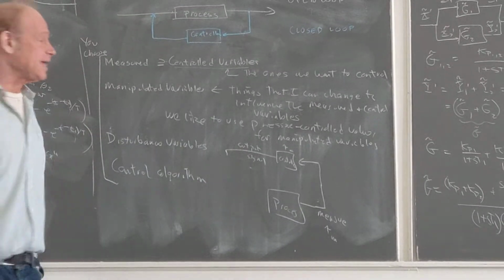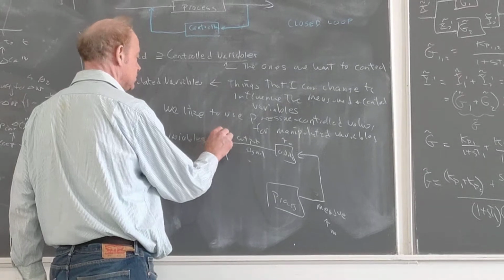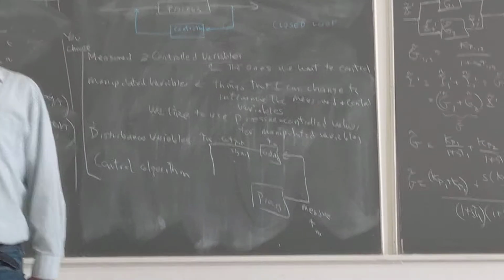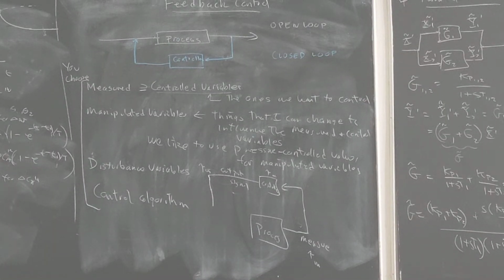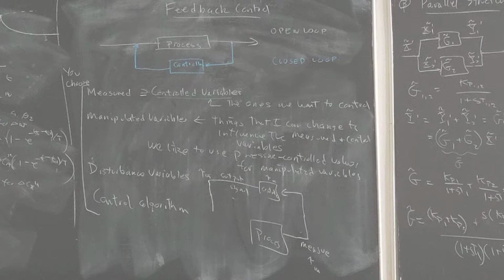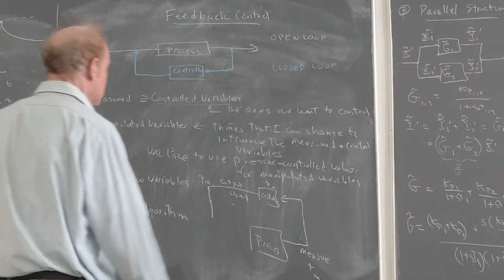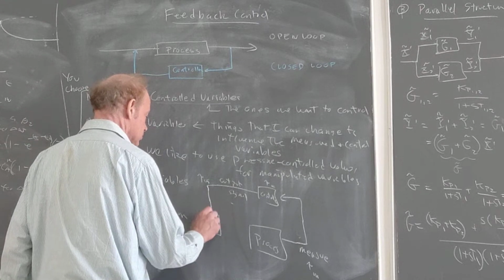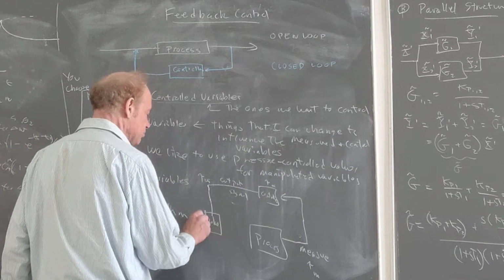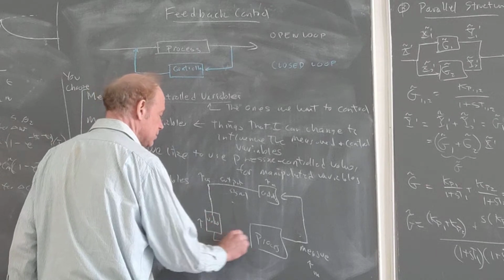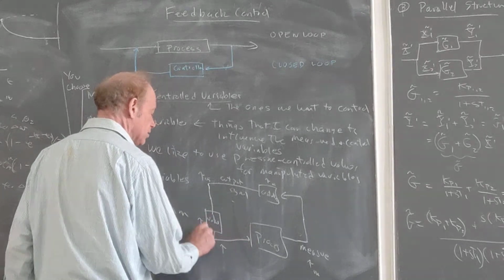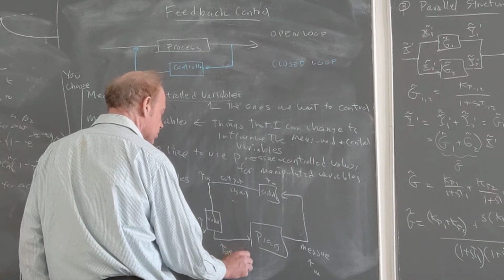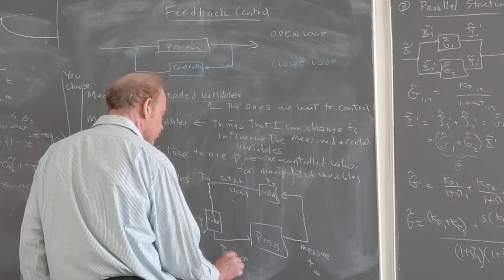That output signal takes time to travel. That output signal could be an electronic command to change the pressure to open a valve. And then I have the valve. So there's a time scale for the valve to react. And then there's a time scale for the effect of the valve. Change in flow rate.